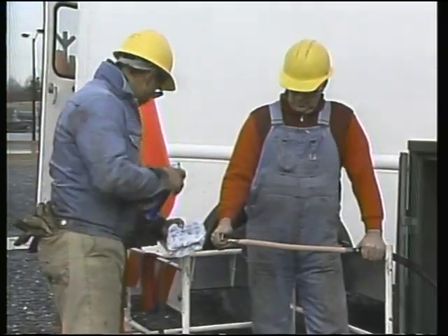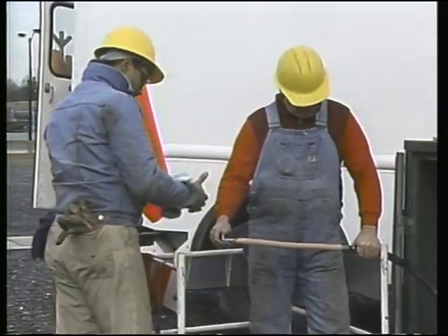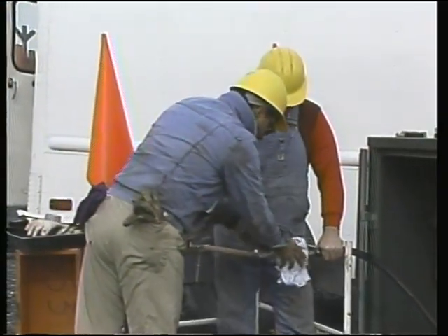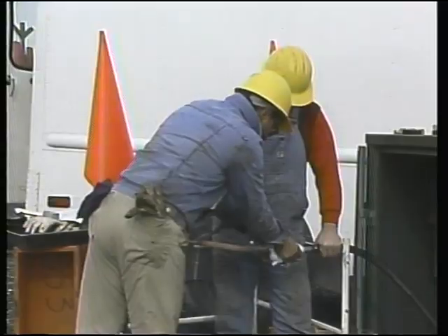Next, the cable insulation is wiped with an approved solvent and a clean cloth to remove conductive contaminants. With the connector in place, the next step in the process is building the termination using various types of tape. The termination instructions provide detailed information about the types of tape that should be used and the methods for applying them. The first layer to be applied is a rubber insulating tape.